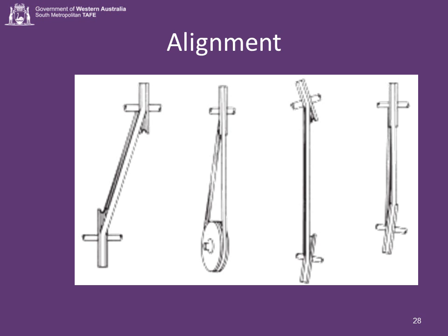The first step is to level the shafts. This is done by placing a level on each of the shafts. Then shim the lower side until the shaft is level. Next, make sure the shafts are parallel. This is done by measuring at different points on the shaft and adjusting the shafts until the distances apart are equal. Make sure that the shafts are pulled in as close as possible before performing this procedure.